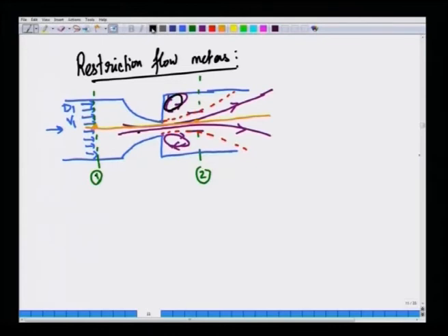Okay. So, this is admittedly an approximation. We will correct for this approximation later, because remember that the Bernoulli equation is valid for a hypothetical inviscid fluid, while no real fluid is inviscid, that is, no real fluid has 0 viscosity. So, there will be losses. Now, losses are neglected to begin with and they will be corrected for later using an approximate method.